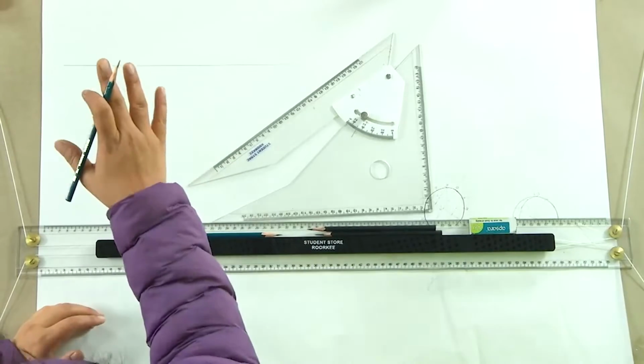What we see in this case is that when we see it from the top, we will see the true shape because the base is being kept parallel to the HP. So, when the axis is perpendicular to the HP, we will see the true shape of the base in the HP.